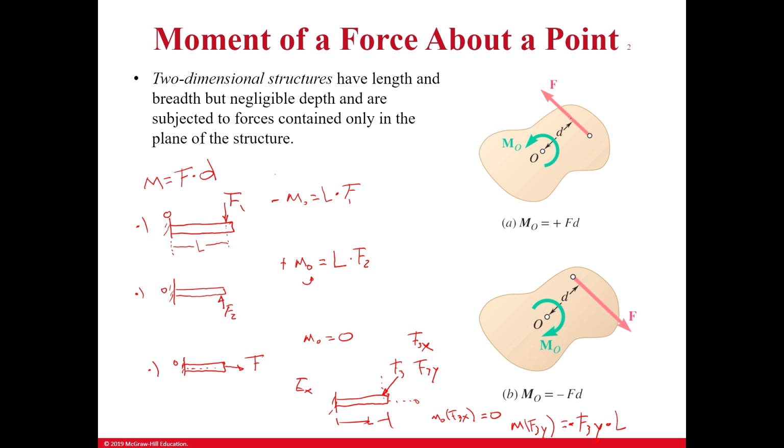Also, the force does not have to be exactly at the point where you're measuring the distance. As long as the force is crossing through that point, you can measure it. Remember that you can move forces around in statics because they're basically keeping the system in equilibrium. And we just talked about the sign. If it's clockwise it's negative, if it's counterclockwise it's positive.